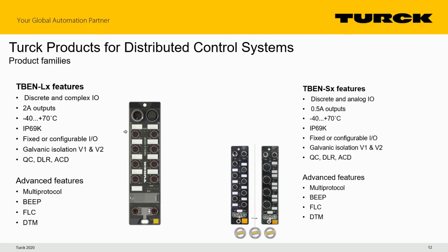So they are very robust when it comes to temperature, vibration, shock, anything like that. These will actually hold up better than I/O inside of a cabinet. They are IP69K when used with the correct connectivity. We have fixed or configurable I/O points, so our digital points can be used as an input or an output.